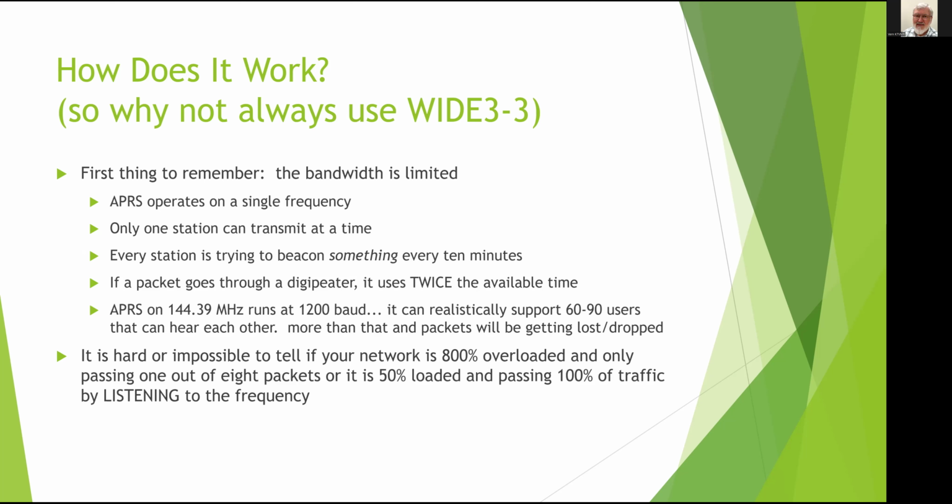So you're listening to your own packet after the first bounce? When you first hear it from the digipeater, yes. You'll hear it come back to you. And in fact, my radio will actually tell me if I have that turned on, which I have turned off right now. But if I send a packet, if I have the sounds turned on, it'll go beep as it sends the packet. And then when it hears the digipeater send it back out, it'll say beep, I received my own packet. Yay, I got digipeated, right? And if I don't hear that, I know the digipeater didn't hear me for some reason. Maybe I'm inside a building or somewhere where I'm not close to the digipeater.